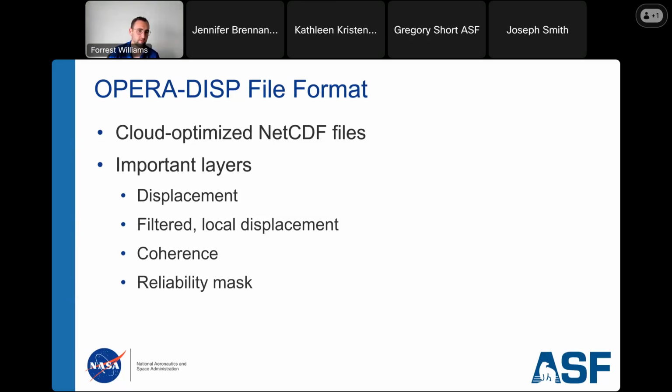The first is the main displacement data set, and this is the key one that actually records the PS plus DS time series InSAR analysis that I've been talking about today. In this data set, you'll see the displacement signature from both long wavelength signals like plate motion and the like, and some of the smaller signals as well, but sometimes those can be swamped out by other impacts.